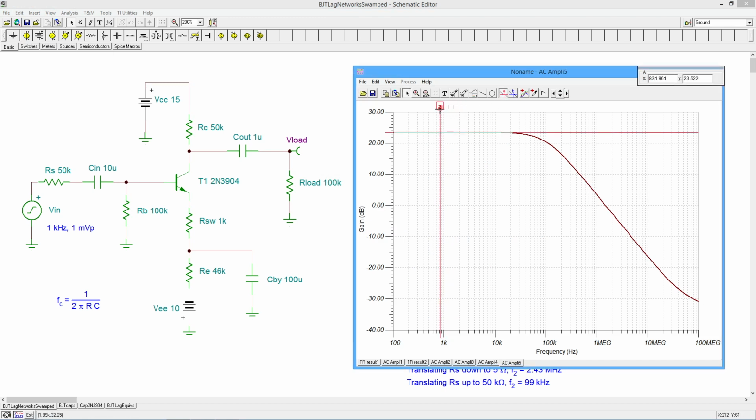All right, so our gain has actually dropped down a little bit, right? We're at 23.5 dB. And the reason is because we're losing a lot of input signal on the 50K. You know, when it was 50 ohms compared to the ZN, it was no loss at all. But now that there's 50K out here, we're going to actually lose a bit of signal. But the important thing is, what is the midband gain? So that's 23.5. So I need to find 20.5.